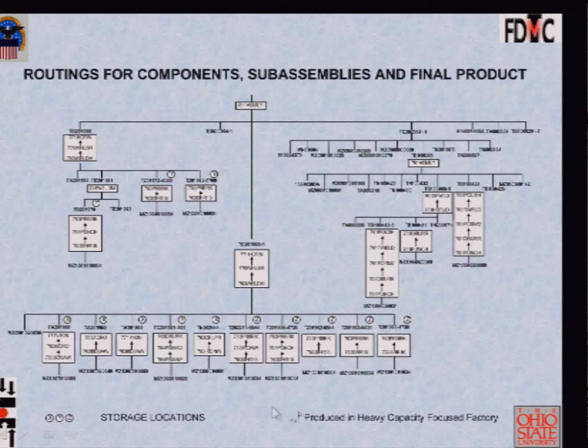that from this initial skeleton of the value stream, you get some sense of where to put the supermarkets, okay? And then more fundamentally, I think you will see where is going to be this major issue of shared resources. See, this particular sub-assembly is built through this processing sequence, but then this sub-assembly is also built through this processing sequence. So like it or not, one of these sub-assemblies will have to wait for the other one to be done. That becomes a scheduling issue.